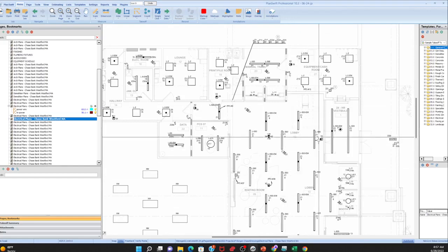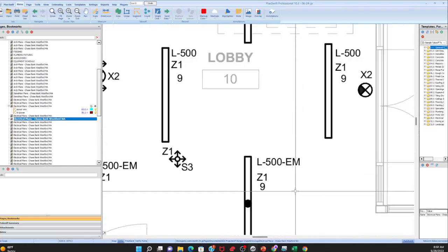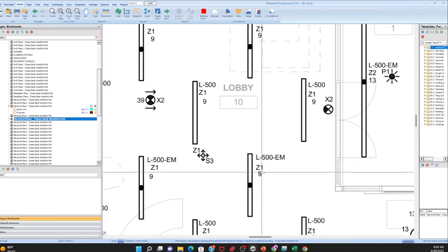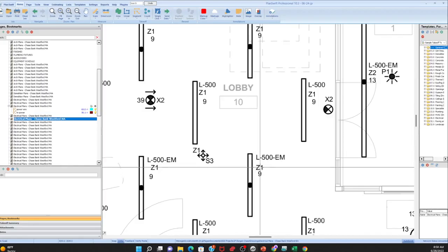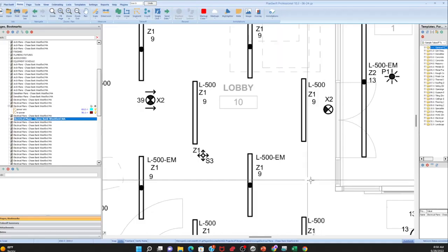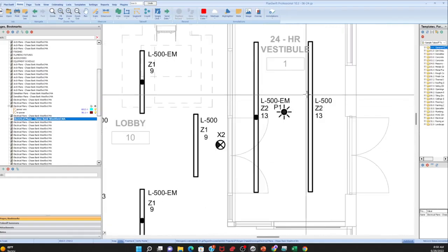Okay. So now we're to the lighting plan, which I always do last because really all we're doing is counting. We're looking at the lighting symbol. So make sure you are differentiating between what they call the light and this thing, right? That is just the zone, right? Because the lighting plan shows us all the lights and how they're controlled. So they're showing the electrician that certain lights are in zone 1, certain lights are in zone 2, you see?